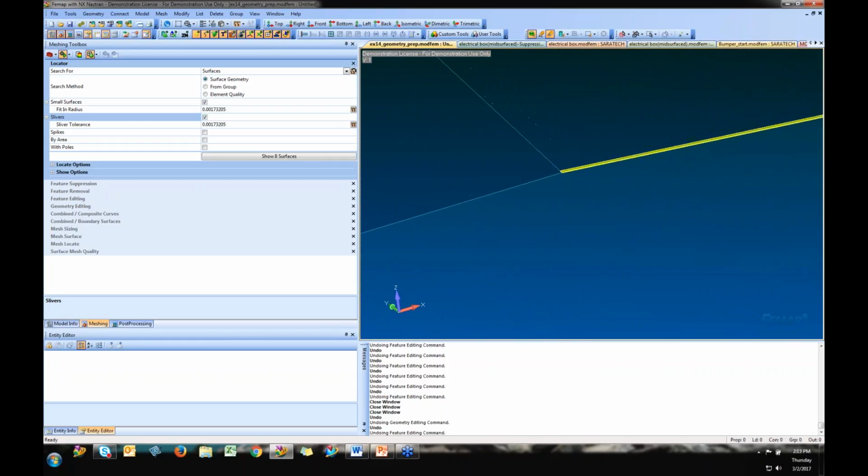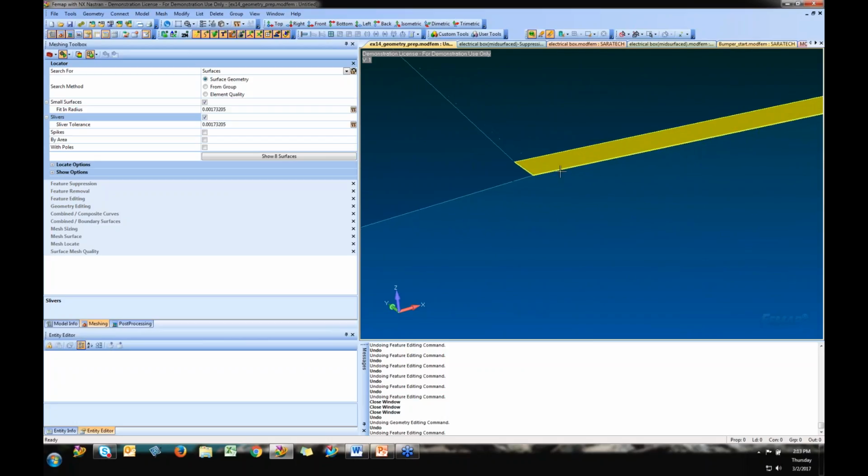So this actually happened due to some CAD. It's so small, and this would be a region where we'd want to combine surfaces together so that the mesher noticed this little surface was connected to the other. So imagine the mesher would have to throw tiny elements in this location, but if we combined it with the surface next to it, we would have a nice clean mesh because it would notice this as one surface.